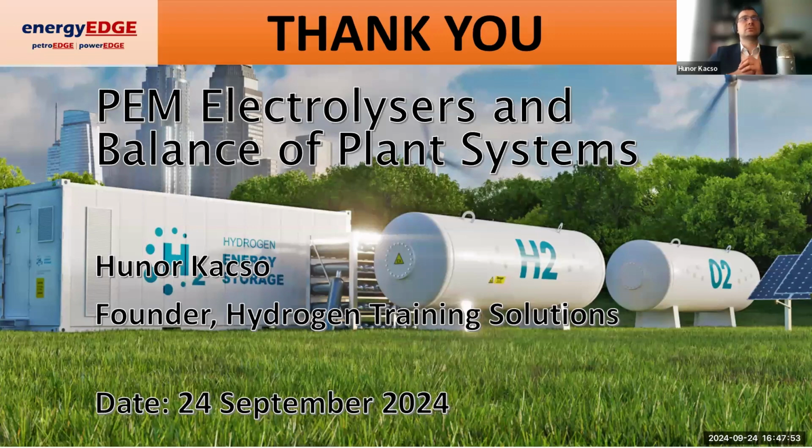So the voltage efficiency, if you don't include heat recovery, can be anywhere from 60% to 70%. 70% efficiency is quite high, 60% efficiency is relatively low, anywhere in between. To generate 1 kilogram of hydrogen, you will typically use between 50 to 55 kilowatt hours of electricity, and 1 kilogram of hydrogen contains 33 kilowatt hours of energy.